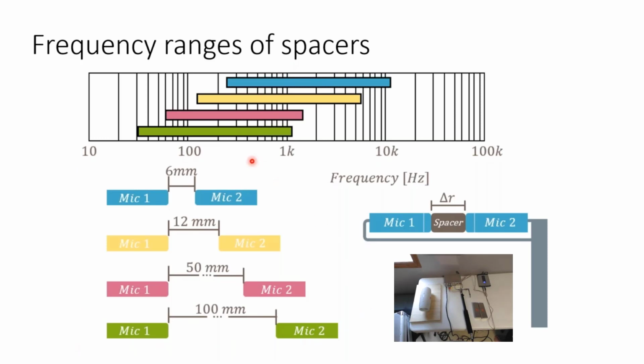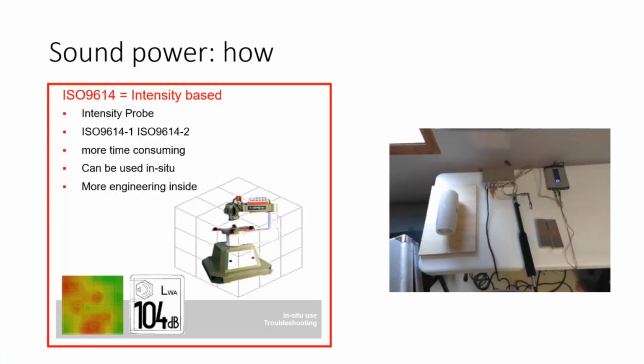There's tons of websites online that'll help you calculate this, and if you're running the TestLab software, there's a place to put in this microphone spacer so that you know exactly what you're getting. So it's just kind of a nice check to double check if you're using an intensity probe. If you've ever used one and you're like, I don't know what the spacer is for, this is what it's for.